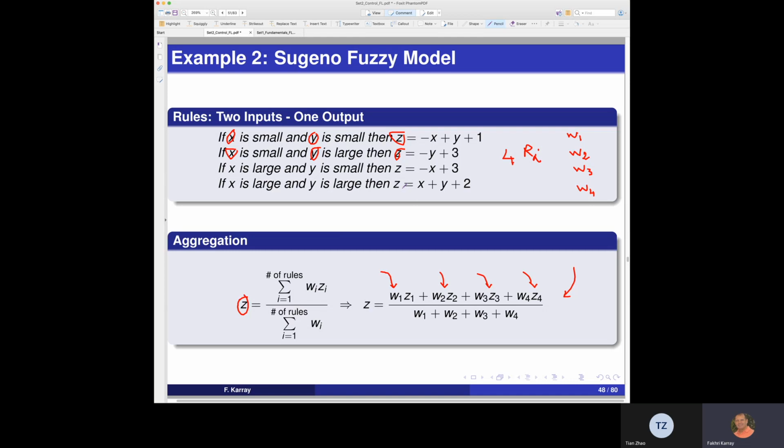So to recap what I just said, there are two types of defuzzification or fuzzy inferencing systems. There is the Mamdani one. With the Mamdani one, we use the fuzzy inferencing as we have seen it originally without any problem, but the issue is in the defuzzification process of the model, because we have to compute, remember, the centroid of area. And as I mentioned to you, the aggregated membership function of the system is usually complex to obtain.